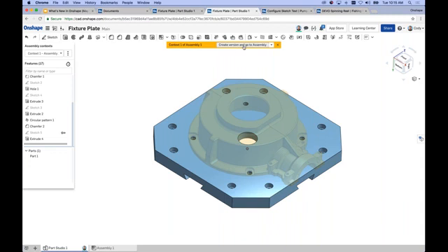And if we intend to update where this came from with these new holes, because it's linked documents, of course, we need to create a version and then go to the assembly. And that is different than if everything's in the same document, right? So important to point out that is a small difference. Now, keep in mind there's also this option for just go to assembly. This is great if maybe the context is wrong, the position's wrong, or you just don't want to create the version at that moment in time and go back to the assembly.